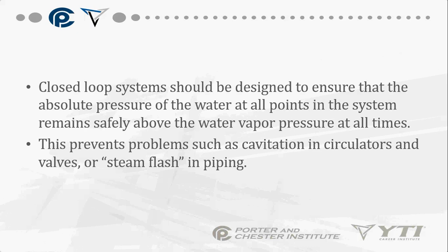Believe it or not, if a boiler does happen to rupture or explode, it can level a house or a building. I personally have seen this happen. They are pressure vessels. We have to have those safeties in there, like your aquastats, your relief valves, your water feed valves. All of those things have to be on a boiler in order for them to work properly.